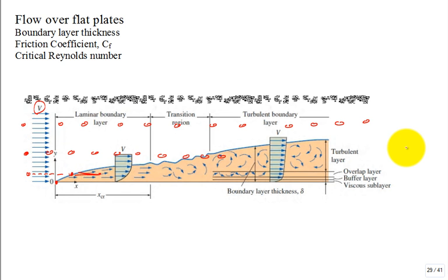So what we have is a region called the boundary layer region over that flat plate where the presence of the flat plate is felt. So what does it do to the fluid chunk that comes right there and tries to skim along the top of that plate? Well, it slows it down. Because that plate is stationary, it has zero speed, there's a no slip boundary condition. So the fluid attached to it or right adjacent to it, that fraction of a millimeter, is not flowing. The fluid is brought to rest right there.